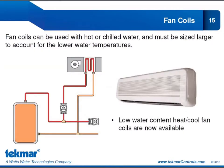So fan coils can be used with hot or chilled water. So it's great for a heat-cool hydronic system. But we have to remember, when we're talking about hydronic systems, the fan coils have to be sized larger to account for the lower water temperatures. Now we also have manufacturers that make low water content heat-cool fan coils, and these operate at reduced water temperatures, so the units don't have to be sized quite as large.